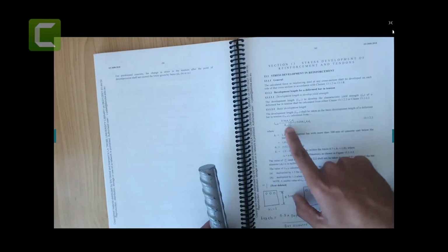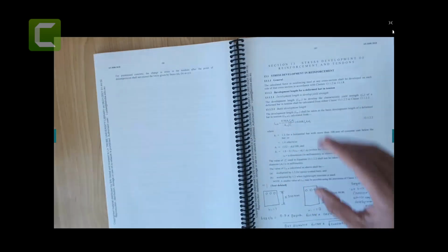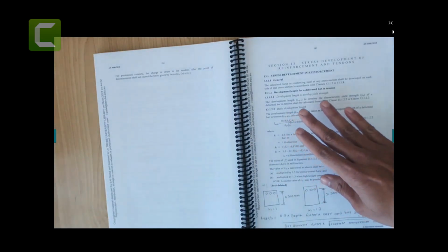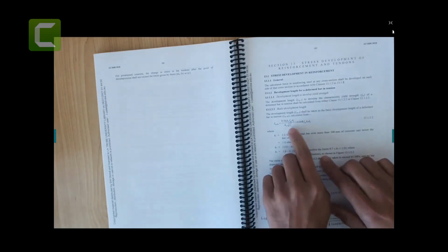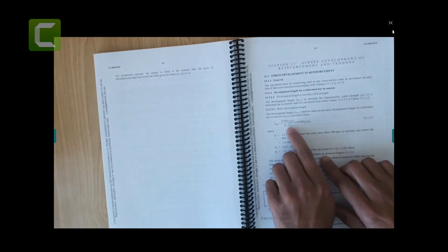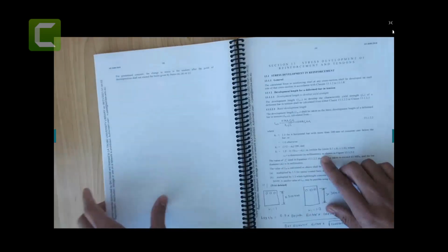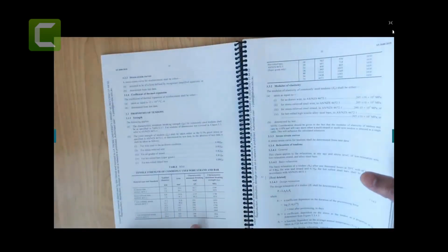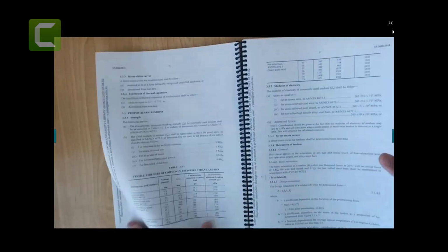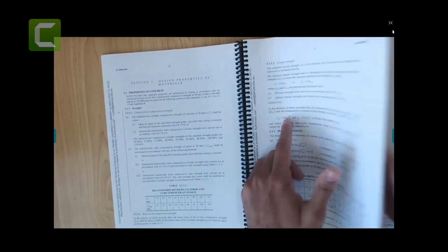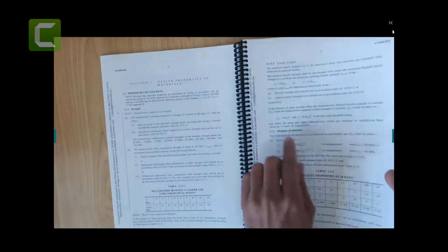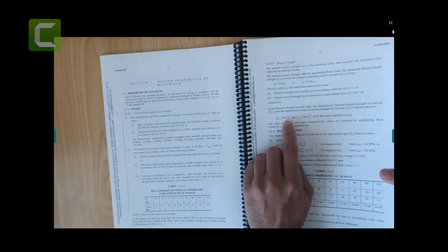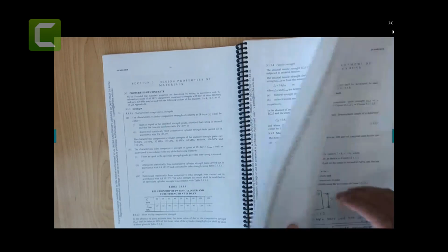That I already explained. The square root of f'c: basically why they put the square root is because they want to make sure we use concrete tensile strength, not concrete compressive strength. If you remember, for tensile strength they generally put the square root. I can show it to you. In here they put the square root there. Someone might say, what happened to the 0.6? Probably they did some calculation here to get rid of that 0.6, but that square root is basically coming from your tensile strength, because your length will be governed by the tensile.